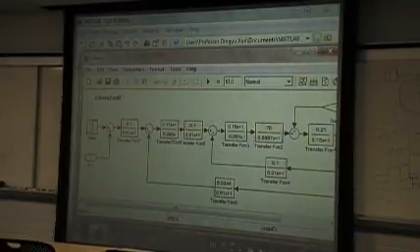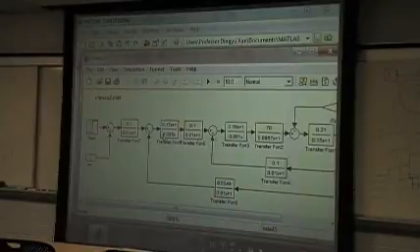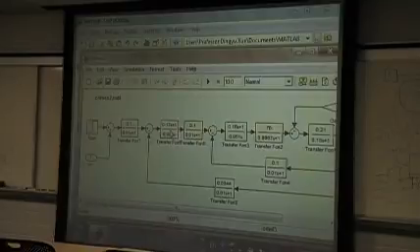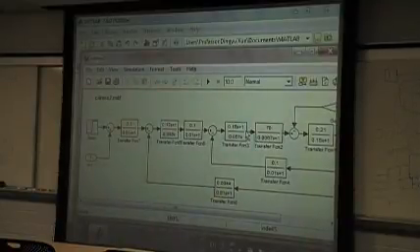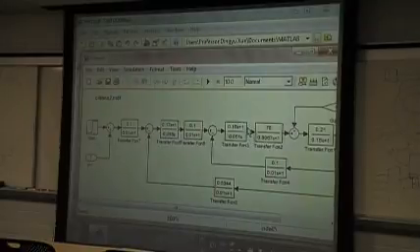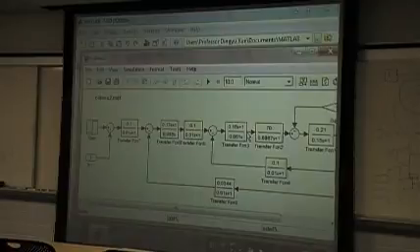You can create a subsystem of the PID controller, so you can use it here and there. But you must be very careful, because if you use the same subsystem, then the parameters of the two controllers are the same. So this is obviously not the one we want. So how can we make these two subsystems independent? The best way is to use the mask technique.